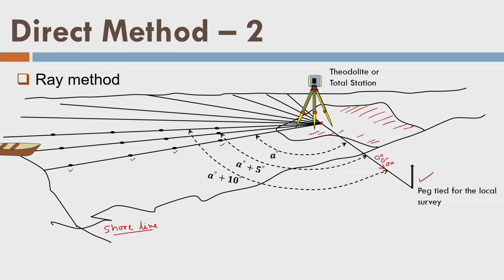So now you are measuring the xy position with the help of the float line, and at every such point where you are observing xy, you are also measuring the sounding position or the sounding measurement. Fine. I think this is the very standard method. Now I can use any instrument for sounding, but we always do it, right? So that is why we say it is not a pseudo 3D survey.